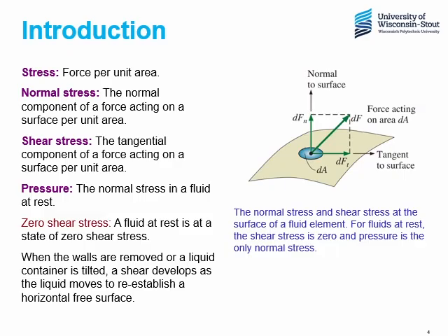Think of the wind pushing sideways on a building. Pressure is the normal stress in a fluid at rest. And here is important: at rest, shear stress is zero. When you tilt the container or remove support, the fluid begins to move and shears develop.